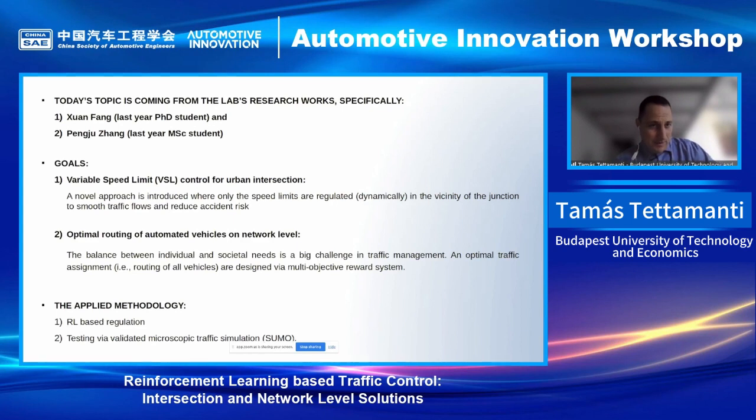The first topic is about network intersection level control, and the second one is the network level possibilities for traffic management. What is common in both research is the applied methodology, which is based on reinforcement learning. Secondly, we love using traffic simulation, so we always make experiments and validation using microscopic traffic simulations, usually SUMO or other software tools.